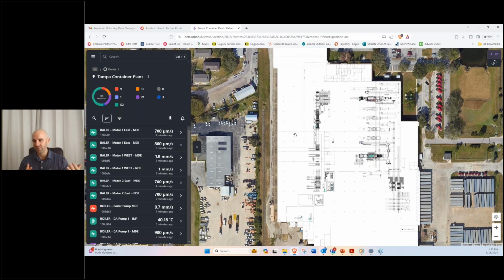That leads me into something I want to touch on anyway: every 30 sensors justifies a free gateway. We could do a facility this size, which is a large cardboard facility, with one gateway, no problem, but they have 100 sensors, so that justifies at least 3 gateways. I'll probably bring 2 gateways on site for the install, maybe all 3, just in case we need them due to a lot of metal in the way.